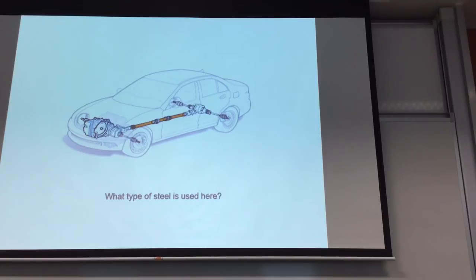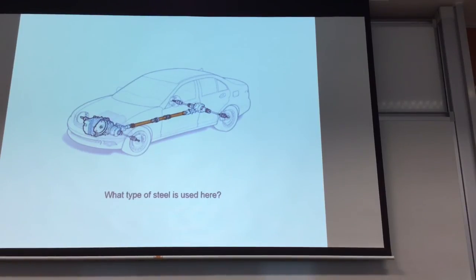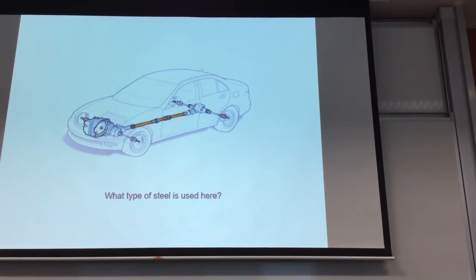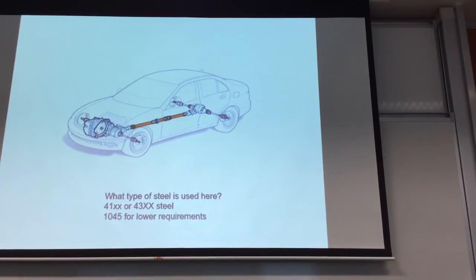Your car axle, what material will you use? Ultra strength, okay, one of this. For your application, I think this one will be sufficient because your shafts, this one should be sufficient. But you do some calculation. So if you want a stronger steel, the common material will be your chrome moly steel. This is your 41 and 43 series.